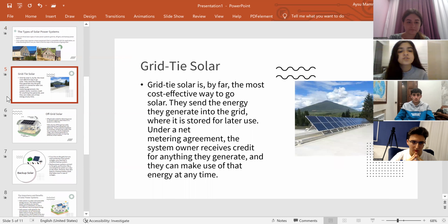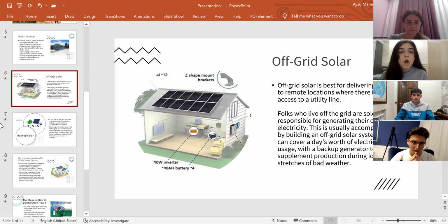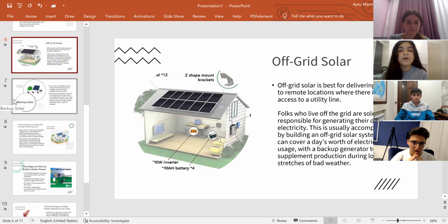Let's firstly talk about the on-grid solar system, also known as grid-tie or grid-feed solar system. This is a solar power system that's connected to the grid and has no batteries connected to it. Secondly, off-grid solar systems. Off-grid systems are the ones that work independently of the grid, but have batteries which can store the solar power generated by the system. As a matter of fact, an off-grid solar system will work even after a power cut, whereas an on-grid will not work.